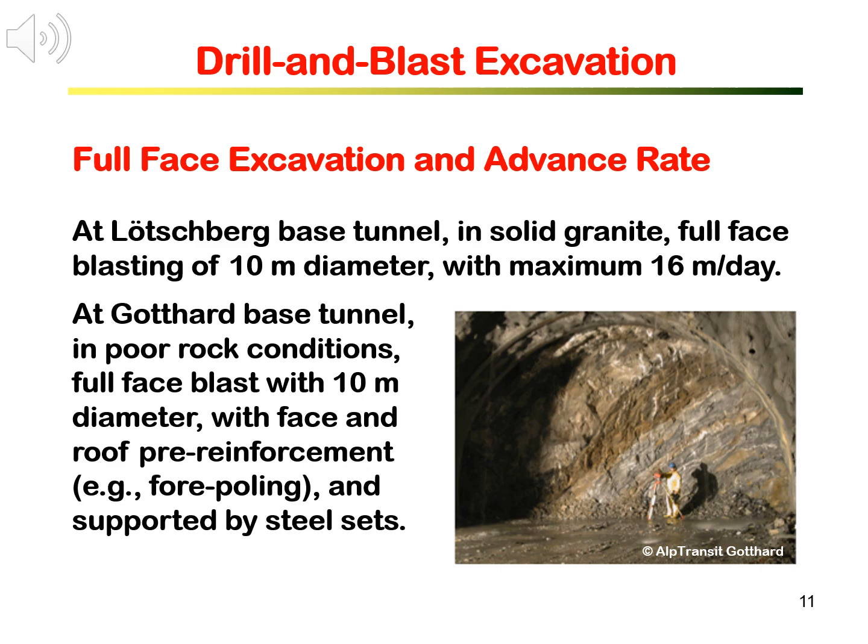At the Gotthard base tunnel, also for railway but in poor rock conditions, full-face blast was used for the tunnel with 10-meter diameter. However, face and roof pre-reinforcement, for example by pipe roofing, were applied before excavation. After excavation, the tunnel was supported by steel sets and shotcrete.